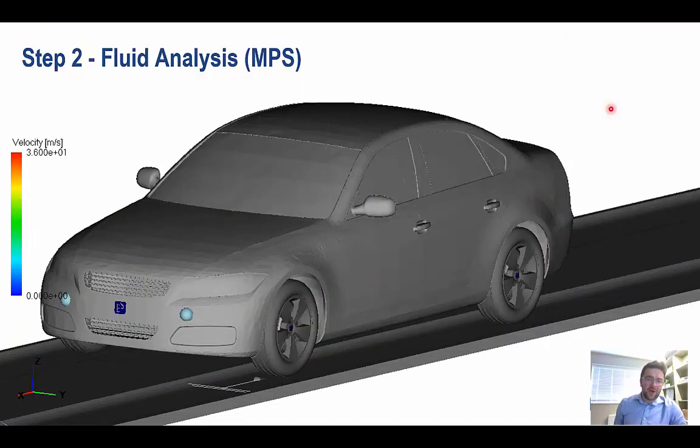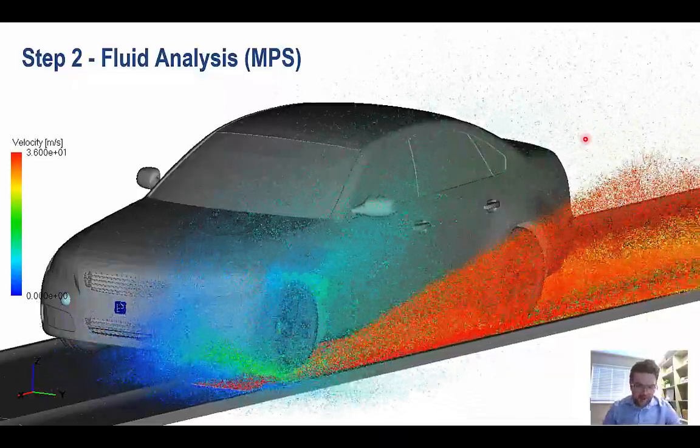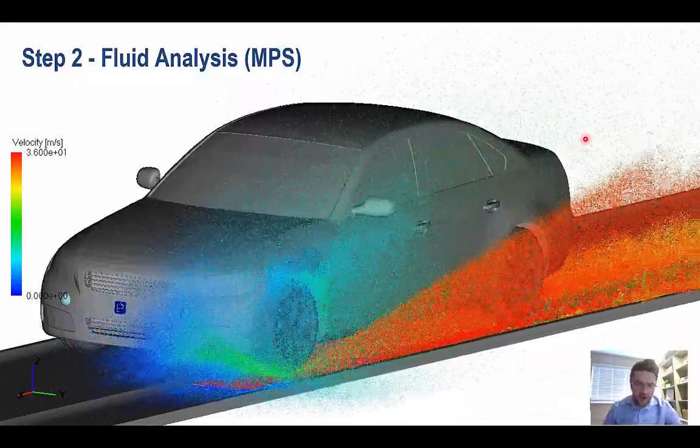Once we have the airflow, we can then apply that to a fluid analysis. So what we're doing here is a standing water simulation. You can just about see at the bottom here, we have an inflow generating particles at the speed that we are driving down the road. We can then see how they interact with the tyre and then subsequently the air, and how they can get deposited onto the car. So what we can see here is fluid getting injected, getting picked up by the tyre, and then moved around by the airflow.